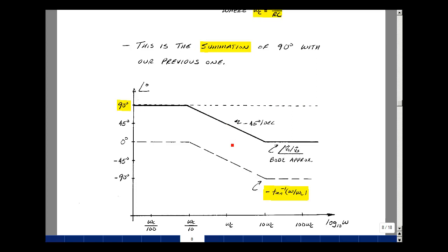And knowing our transfer function, and knowing omega equals omega c, the phase angle response versus frequency as an approximation is 3 straight lines. Where at omega equals omega c, we're at 45 degrees. Go back a decade, we're at 90. Go forward a decade, we're at 0. And our slope here is minus 45 degrees per decade, 0 degrees per decade here, 0 degrees per decade here.